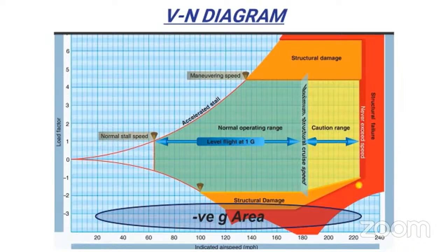Observe that aircraft are generally not made to withstand high negative G load. Two reasons. One is it adds more weight because of structural integrity. Another reason is due to a biological reason called the redout.